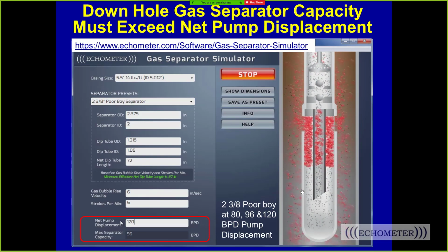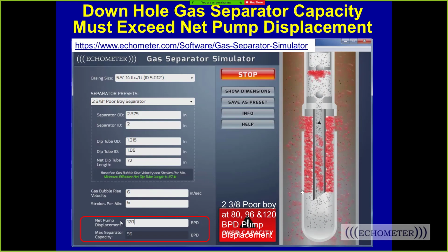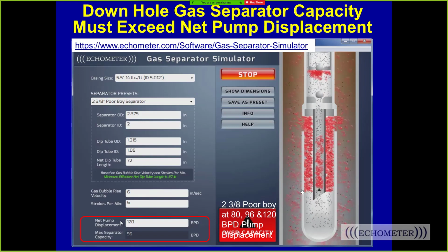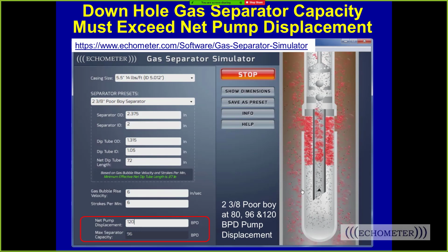Now, when you say the word foam, that's what you get when you pour a beer too fast into a glass. You get all these little tiny bubbles, and you have this head of foam on your beer, and that foam is stable. The bubbles are all about the same size, but if you have gas flowing through the foam, like in the annulus of your well, if the gas rate is more than about 1 MCF per day, it will tear the little foam bubbles up and they won't exist anymore.